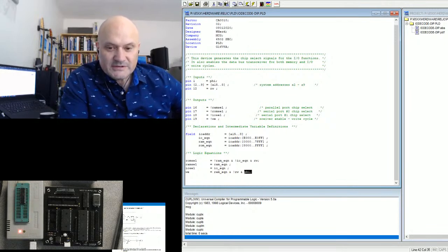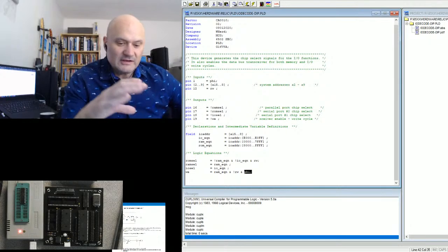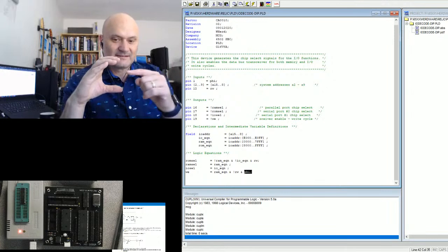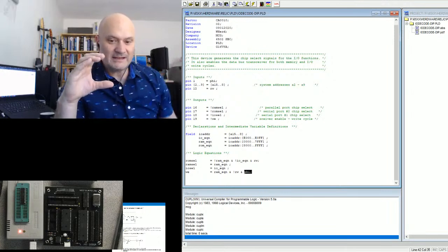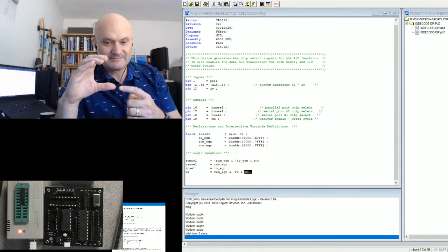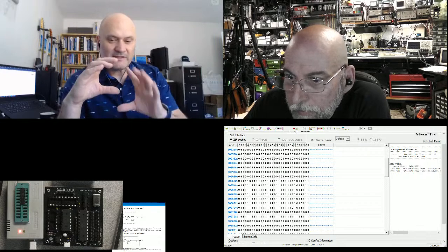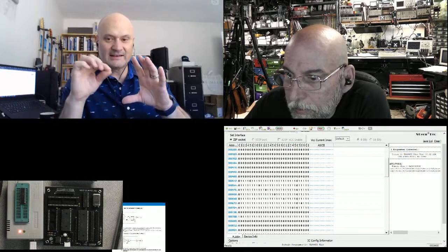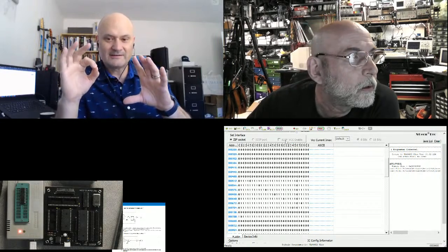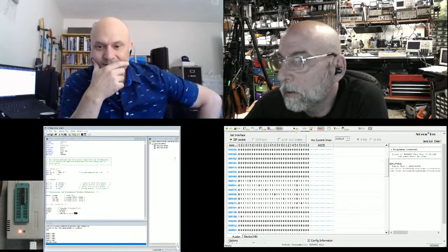Which means you're actually using an AND gate with a clock going into one pin and the read-write and RAM equation signals going to two other inputs to the AND gate, and then and only then will the output go low. Right.